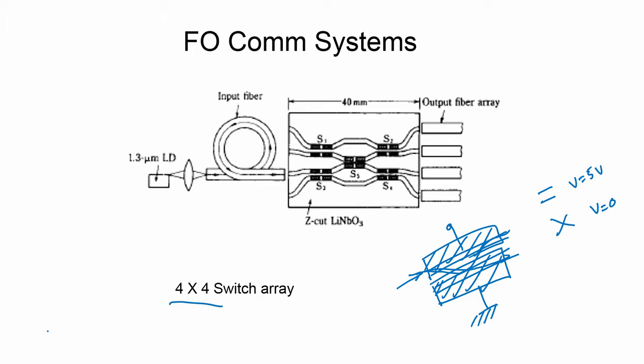There is one additional feature which we have not discussed earlier: there are tapered regions. These directional couplers have to be tapered if you want to connect inputs and outputs. There is, of course, a tapering between these sections which we are ignoring at this moment for conceptual purposes, but in a practical situation we need to consider the coupling of light between these and then adjust the voltages or the coupling lengths accordingly. For the time being we will assume that the functioning of these directional coupler switches is as discussed earlier.